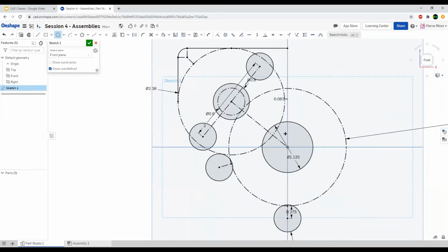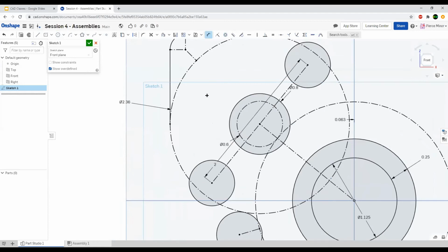But now we have to, oh no, there's actually a couple other things I have to do. So the bearing, it's not just floating in space, right? We have to actually create something to hold the bearing. This is the central hole for the bearing. However, I want to have another circle going out from there. And let's make this circle 1/4 inch larger than the bearing. And then since we need more or less the same for the motor, make another circle here. This will go out. Dimension 1/4 inch.